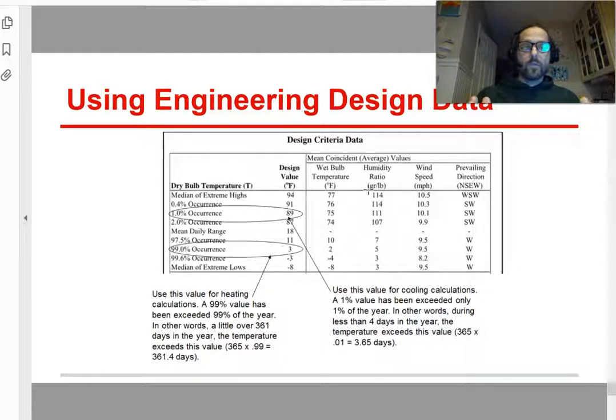You take all the stuff that we've done, the R values and the U values of all the surfaces, and you say, when it's that hot outside, how much heat is going to come in through the surfaces? And you also take into consideration air leakage and so forth. Then that's how much heat my cooling system has to be able to remove over the course of 1 hour.